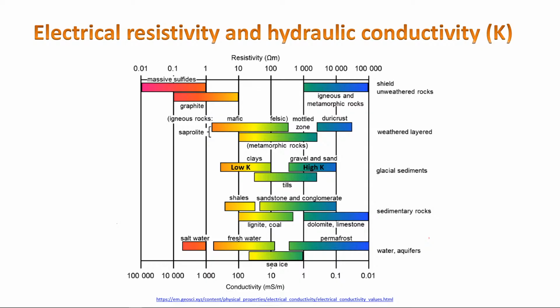Environmental engineering, it could also be used to map a contaminant plume, like monitoring leachate in a landfill site, because leachate, as a liquid, will have a different electrical resistivity value than nearby fluid. So you can monitor leachate, for example, in a landfill site. That's one application.